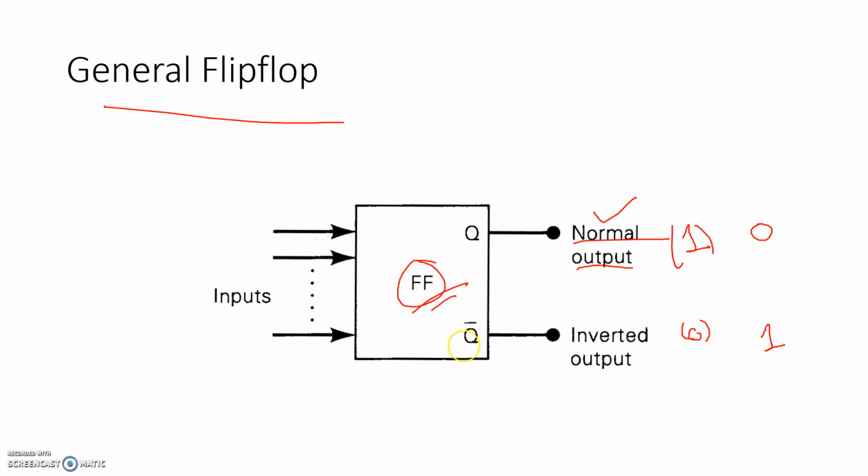This bistable multivibrator is called a flip-flop. Don't consider latches and flip-flops the same. A latch is level triggered, a flip-flop is edge triggered. Later I will discuss in detail. I have just given a generalized introduction as flip-flop, but there are two memory blocks: one is the latch, another one is the flip-flop or bistable multivibrator.